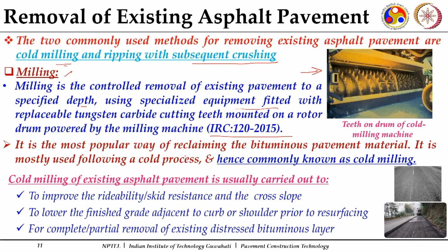Because of this milling machine, recycling has also become quite popular and easy to do. It is the most popular way of reclaiming the bituminous pavement material. It is mostly used following a cold process, and that's why many times you will find that they mention milling as cold milling, because it's a cold process.